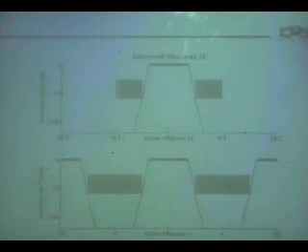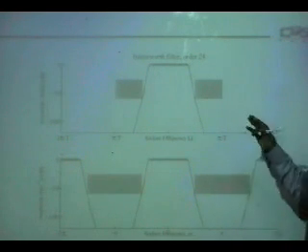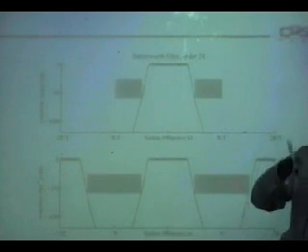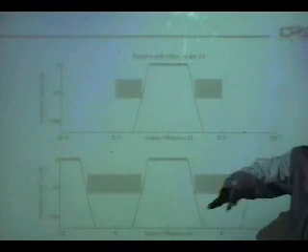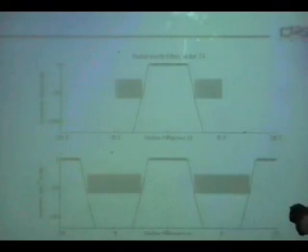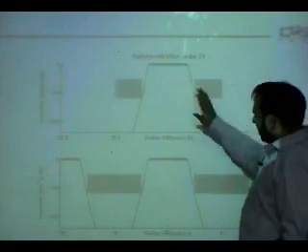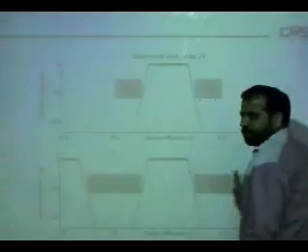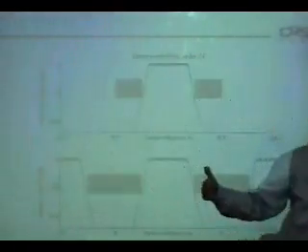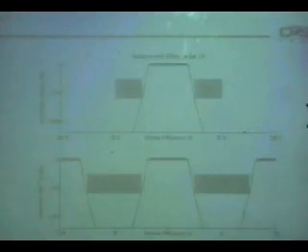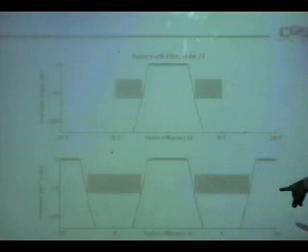So this is the effect of aliasing. Let's say you are designing a filter, and Butterworth helps, because Butterworth filters are smoother, so they just go down, smoothly decaying and dying. So it is a 24th order Butterworth filter in the analog domain. Once you make copies of it, a copy here, a copy here, a copy here at every omega s, it still satisfies. So the discrete version also satisfies, right?